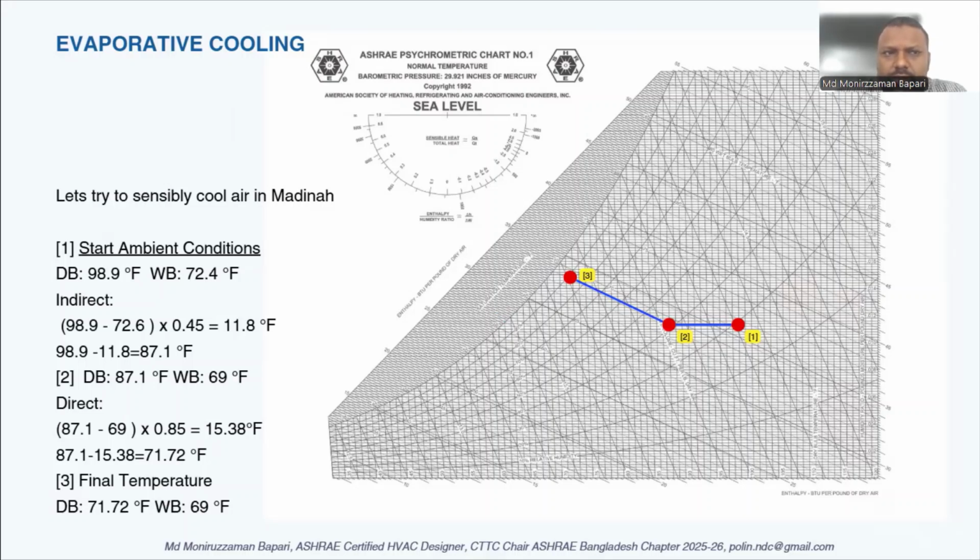However, evaporative cooling is more efficient in large spaces and open spaces, obviously. So good luck in calculating evaporative cooling and doing the sizing, and the psychrometric chart gives away all the data that you need to design a good evaporative cooling system. Let's move forward.